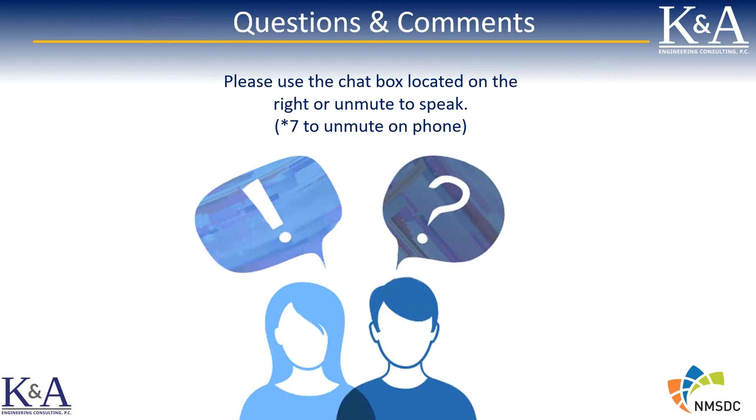As far as the data collection that you need, you basically want to collect all of the information in real time and save it, not continuously, but at least establish a baseline behavior for the substation. Collect enough data so you've established baseline nominal behavior for the substation.